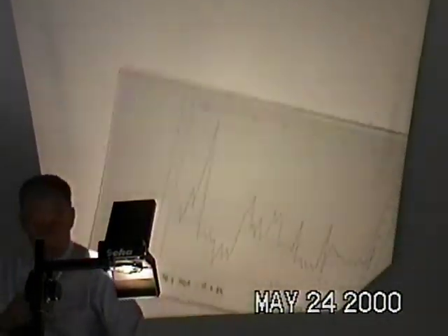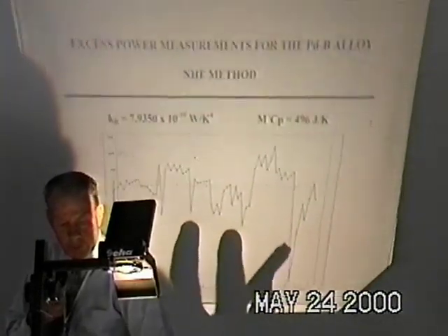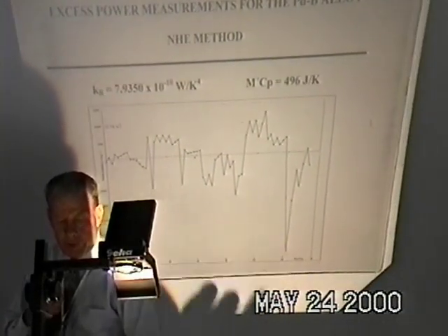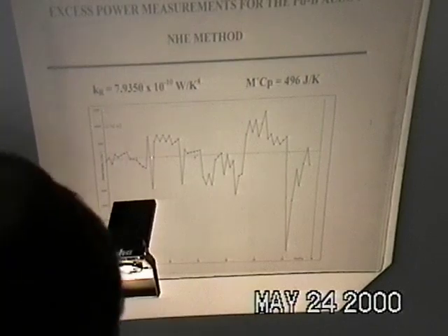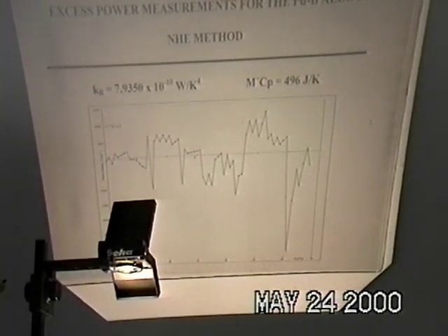Now, if you look at what Japan reported, what their data shows, they come up with a much smaller radiative heat transfer coefficient because they use that first heating cycle where there is positive feedback, therefore large errors. Therefore, they came up with a much smaller constant, and they use a much larger value here.